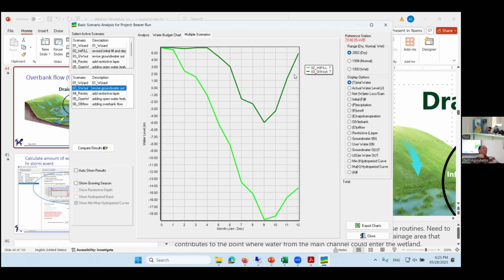Very well, but I'm asking this after the design, and we do it, does it work well, and how well? I mean, I can also put some nice equations, like code, and say it will be dry in 9 months. If you want to validate this, basically what you need to do is measure the water level. If it's above the surface, you need a floating system to measure water above the surface. If it's below the surface, because it gets dry, you need a way to measure. There's a little PVC pipe and a floating device. You can measure the water level below surface. So it's easy to validate. Very easy.